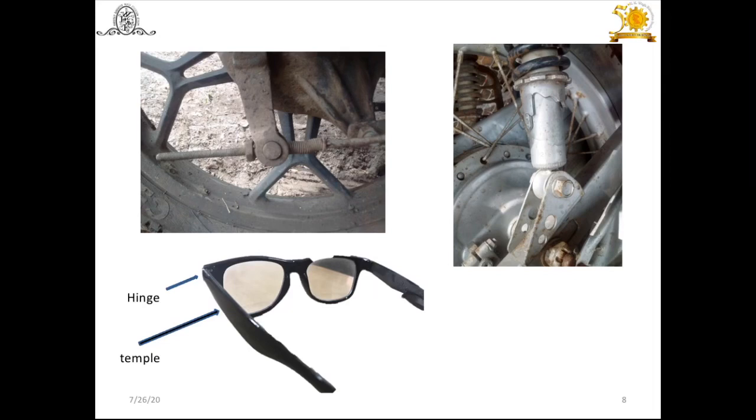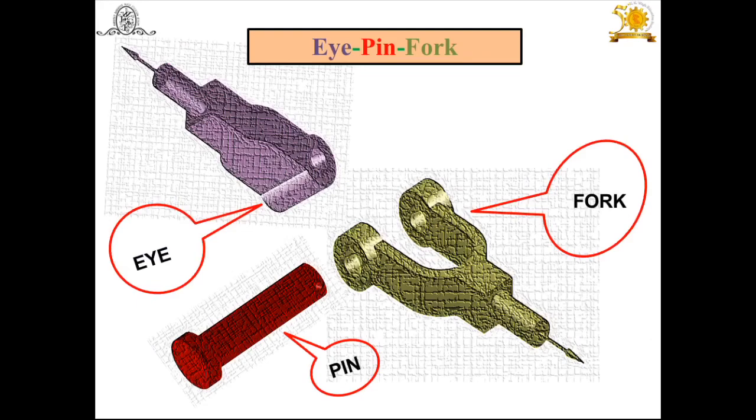Now let us see the advantages of the knuckle joint compared with other simple machine elements such as the quarter joint. The knuckle joint offers these advantages. Its design is very simple. It consists of few parts, that's why manufacturing is also simple. Then assembly and disassembly, or dismantling of the parts of the knuckle joint, is quick and simple. We just have to remove the split pin, and we can easily take the knuckle pin out from the eye and the fork.